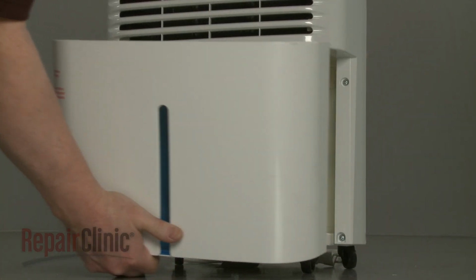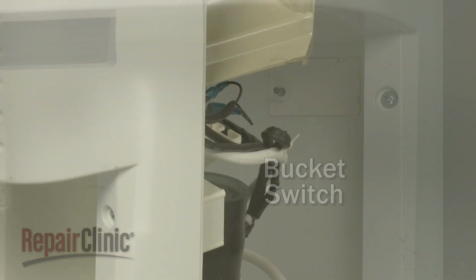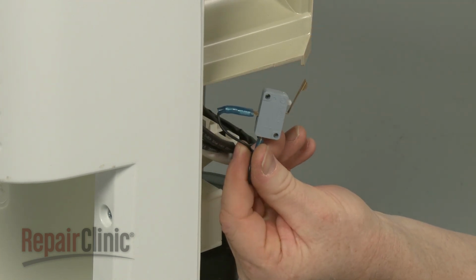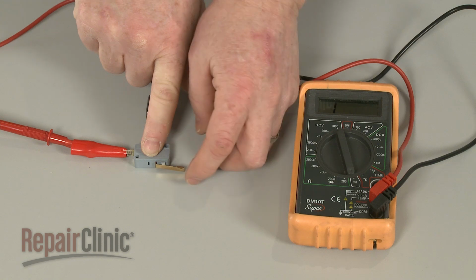Most dehumidifier models are equipped with a bucket switch that will prevent the appliance from running if the bucket is full. If you suspect the dehumidifier should be running when it's not, the bucket switch may be defective. You can use an ohm meter to test the switch for continuity to help determine if the switch is functioning or not.